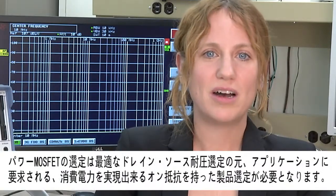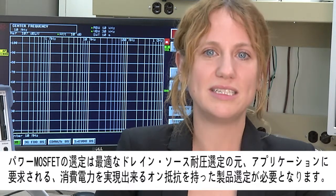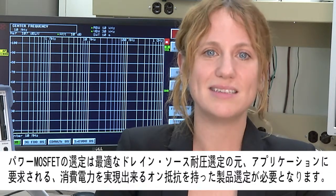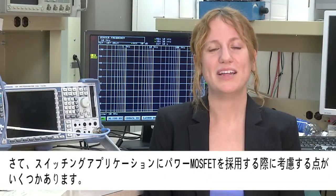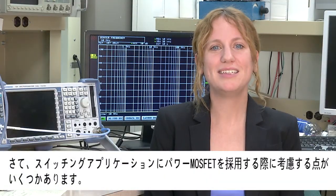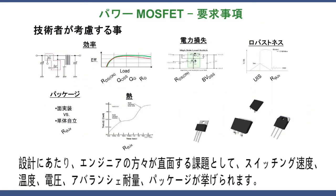When you select a power MOSFET, make sure that you select a device with both drain source breakdown voltage and on resistance matching your application requirements. But before you select a power MOSFET for switching applications, you would need to understand the following additional characteristics. There are several challenges you need to consider: switching speed, temperature, voltage, avalanche capacity, and package.